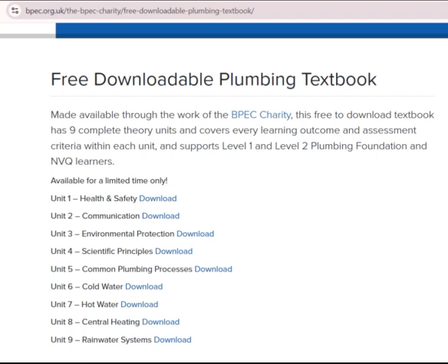C. Systems using combination boilers. 5 underfloor heating systems. 1 pipe low pressure systems. 1 pipe systems use a continuous loop of pipe work that travels to and from the boiler. Each heat emitter was taken from the single loop.